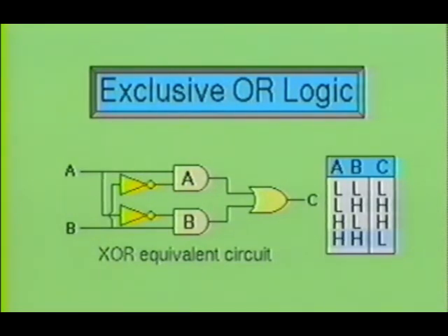As you notice, the truth table shows there will be a low output. When input A is made high, it feeds a high signal into gate A and a low signal into gate B. And when input B is made high, it feeds the second half of gate B with a high signal and the second half of gate A with a low signal. Since gate A has a high input signal and a low input signal, it produces a low at the output. In the same respect, gate B will also produce a low output since it also has 1 high input and 1 low input.